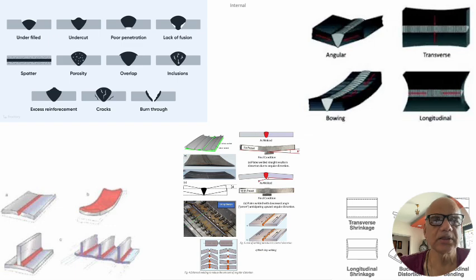Smooth transition is not a stress riser and it is good. Code recommends 1:3 taper for any smooth transition in dissimilar thicknesses, or wherever you have transitions in the nozzle or in our other areas, in the pipelines or in the structural members.